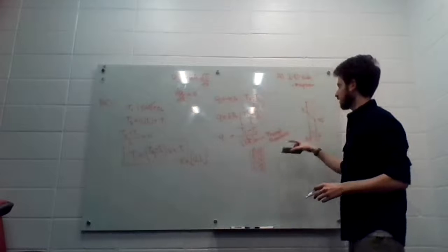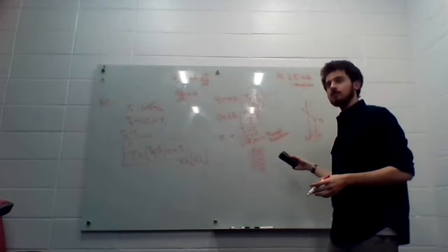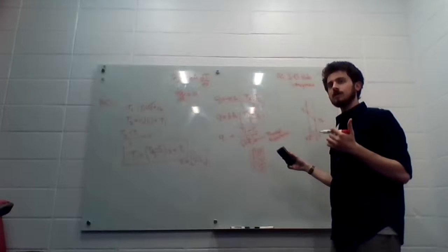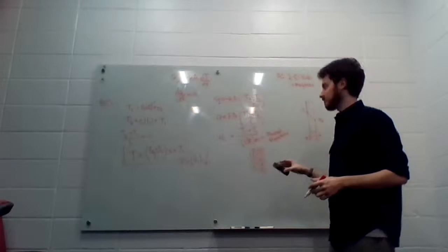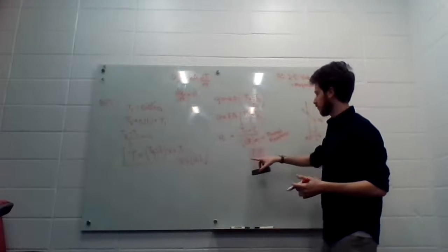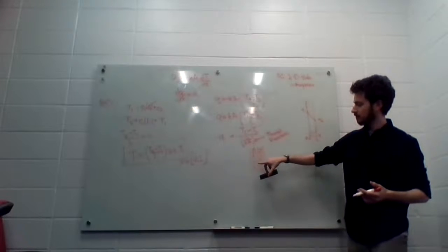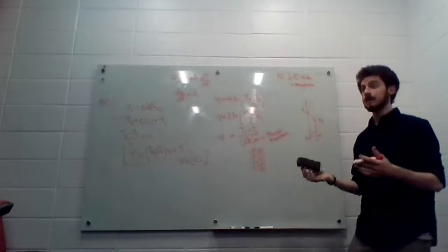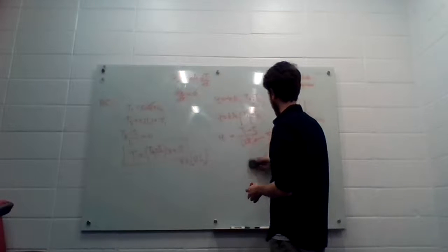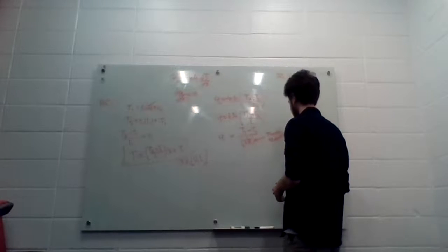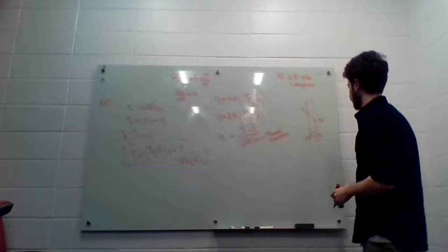So that's thermal resistances. That's the first reason they are useful: you're describing the material independent of the temperature difference. The second reason is when you start stacking up materials, like I showed you here, where you've got gypsum and wood and insulation, all these different things, you can stack the thermal resistances. We are going to demonstrate that that works.